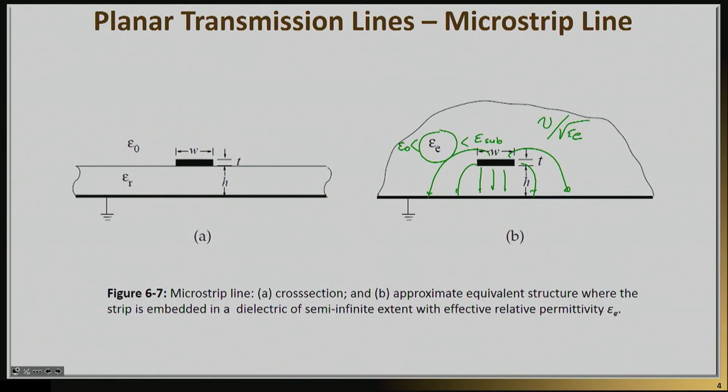described here. The fact that in real life you don't have a uniform medium, but rather you have a non-uniform medium where the electric field exists, essentially introduces what's known as dispersion. So dispersion is essentially an effect that allows different plane waves to propagate at different velocities. So a frequency, for example, of 10 gigahertz will have a different propagation velocity than a frequency of 1.